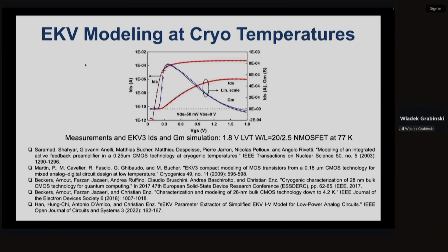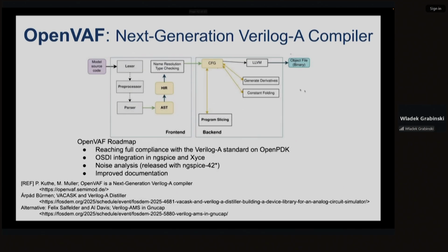It's about the Verilog-A model application for cryogenic temperature level simulations. You can review all references afterwards. Having defined your model, I was showing a MOSFET example, but using Verilog-A, you can define any device, semiconductor device, active components or passive components, including resistor, capacitor, spiral inductors.